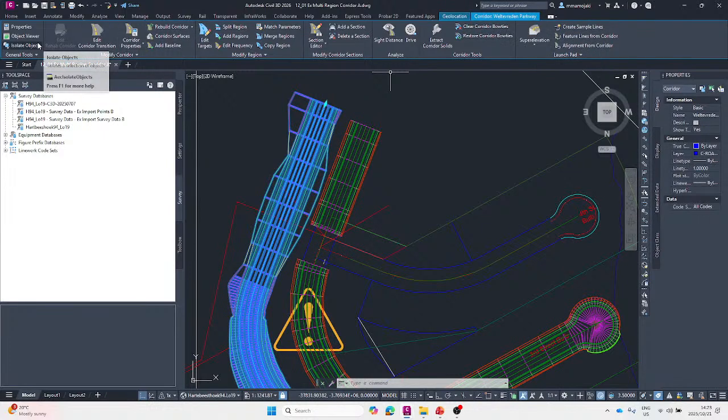And then you will see the ribbon will be different, in the sense that we now have different panels from the ribbons that we usually have when you've selected the home tab, the insert tab, the annotate tab, or the modify tab. So that is what we call a contextual ribbon tab, and it only appears when you have selected an object within your model space.